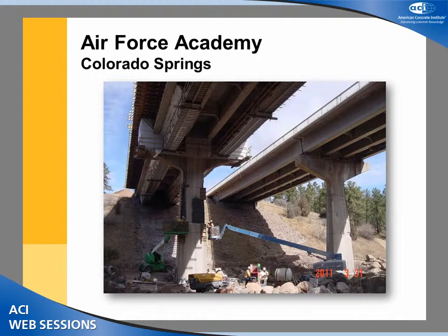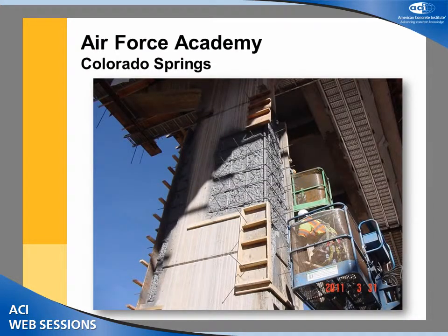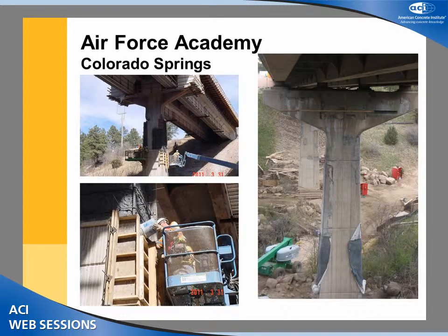Some idea of the access area limitations. If you see the guide, this area is actually the section that was repaired. I think I have a close-up picture that probably gives you a much better idea. And the guy is basically mixing it up, and they will be in the next picture. You can see the material is going to be poured right here. So a lot of concrete was being repaired, you can see, through an SCC pre-bag mix very successfully in restoring these Air Force Academy bridges for the U.S. Army Corps of Engineers.